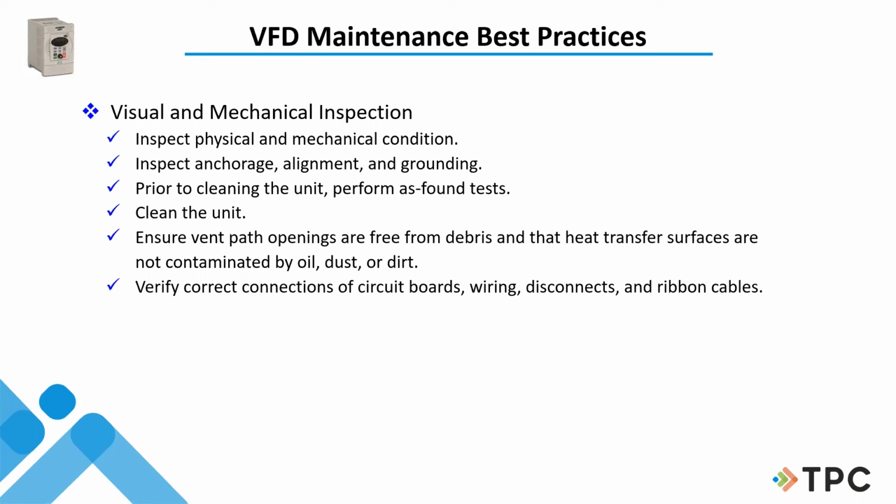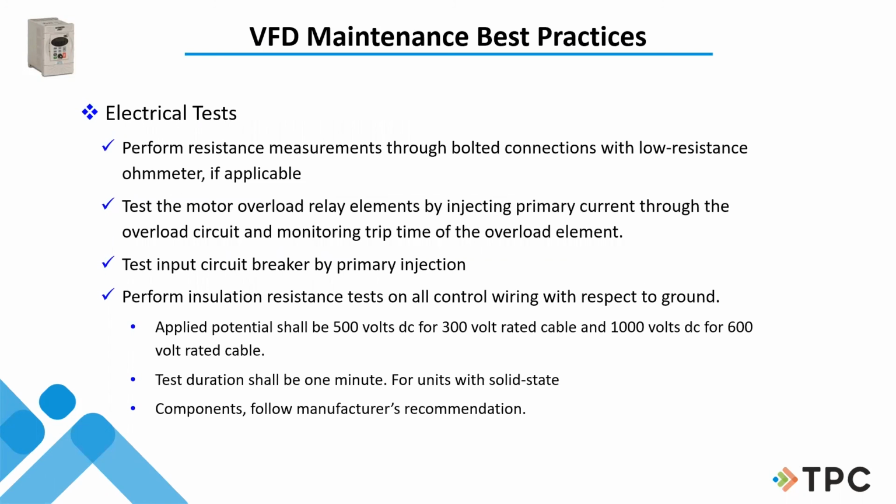I mean, you can PM your way out of any problem, but if a bunch of dirt and dust gets on the heat sinks of the drive, then it's not able to dissipate that heat. It'll overheat and shut down. So you have to do some maintenance and maintain it to get rid of that.